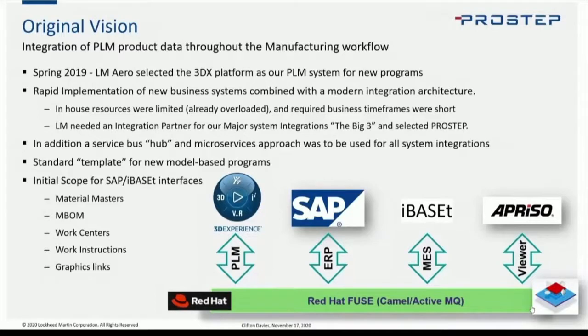But for this project, to try to get the essentials into place, our interfaces had to deal with getting fundamental part information down to SAP, so the material masters and the MBOM, getting work centers from SAP back up into 3D Experience, where we're doing all of our detailed planning, and then bringing work instructions and links to the graphics down to IBase-T for execution in the MES system.